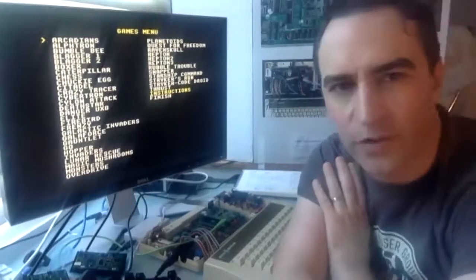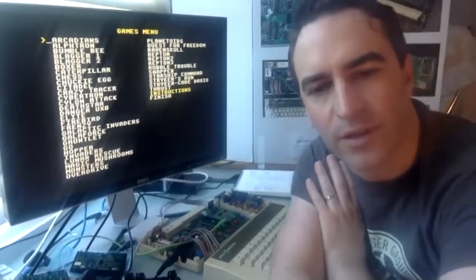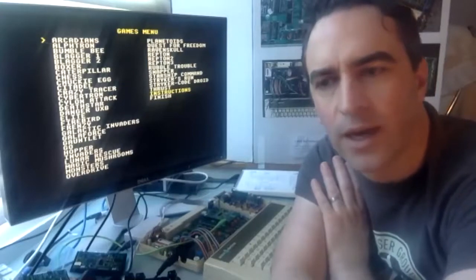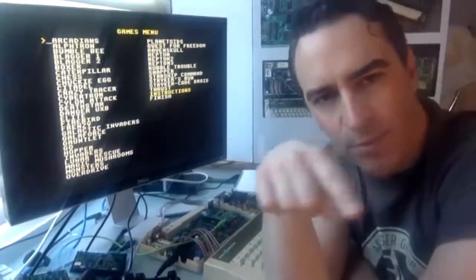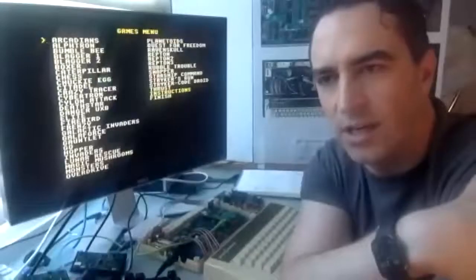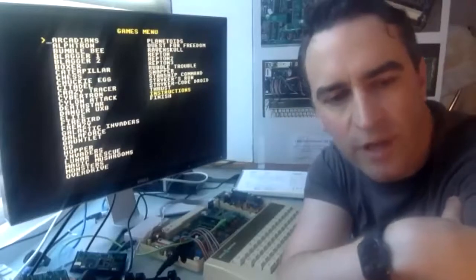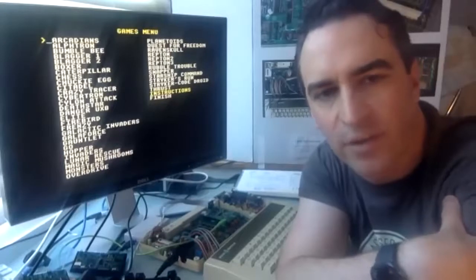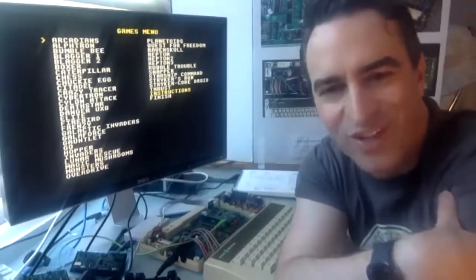I didn't talk about this earlier, but the cassette output from the Electron is an interesting thing. It's got like four levels, so it tries to approximate a sine wave in a blocky kind of way. I was thinking of using a couple of pins in a little resistor ladder to do that, and then I realized that I could just PWM it and make it as sine-like as I wanted. Turned out that feeding a square wave into a cassette recorder works just fine.